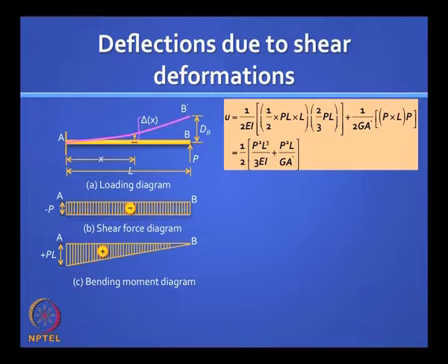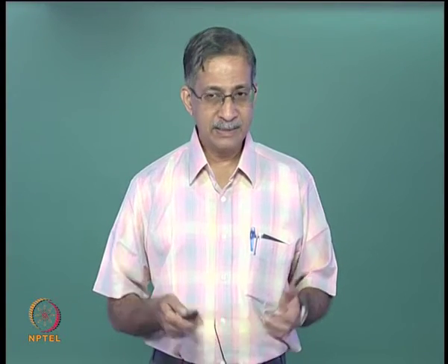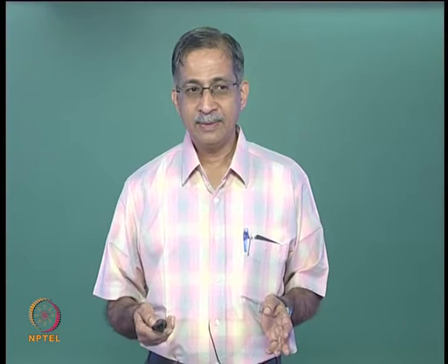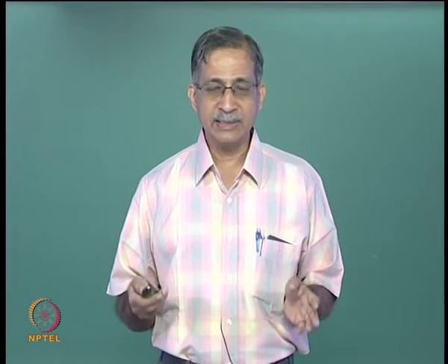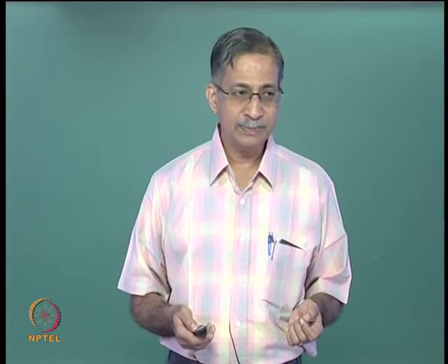So if you look carefully, this part where we multiply the bending moment diagram by itself is the part that comes from flexural strain energy, and this part is the part that comes from shear strain energy. And so the total energy would be given by this expression, where you have both flexural rigidity and shear rigidity G A dash. Now this we can equate to what? This is strain energy in the system. Net internal. The total external work, the real work, which is equal to?